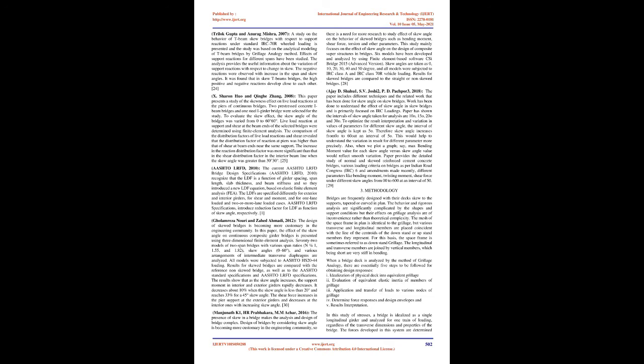AASHTO Standard 1930 introduced an S over D equation for the load distribution factor, LDF, which was a function of girder spacing only. This code does not consider the effect of skew angle and bridge continuity. Finite element studies, however, have shown it to be unsafe in some cases and too conservative in others.